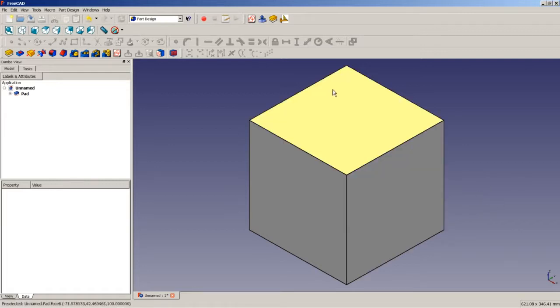So the next thing would be our pocketing. We would not use several single pockets to make an efficient parametric model. We will use a revolved profile and an array, and then doing a Boolean cut and using clones to get the rest to pockets.